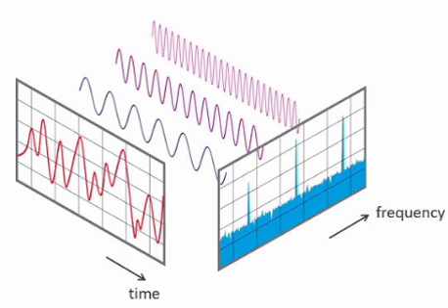For a two-sided signal, the ROC is the combination of two regions. For stability, the ROC must include the imaginary axis, that is, the j omega axis. The solution of the Laplace transform is unique only when the ROC is given.